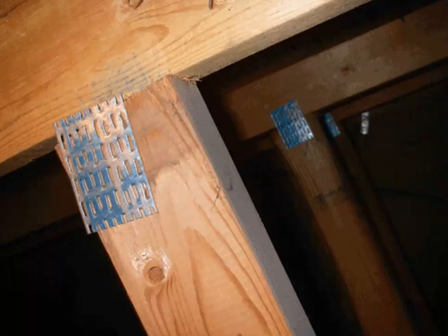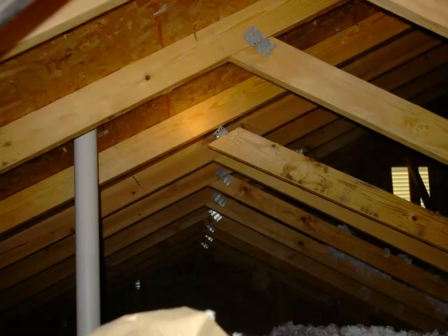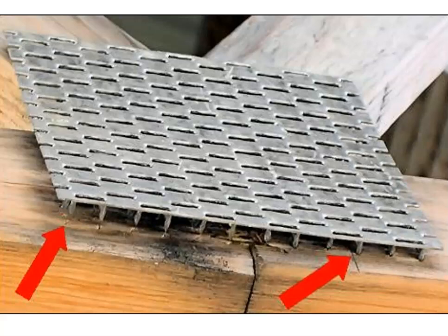And now some more mundane pictures of what goes wrong with carelessness in the manufacturing process. Gusset plates that are not placed properly, so going up looking in attics. Tensile forces have pulled this one apart. These are the razor sharp gusset plates, but some significant forces, some loading or something happened here where this actually pulled away from it. Same here. So quality control could be an issue.